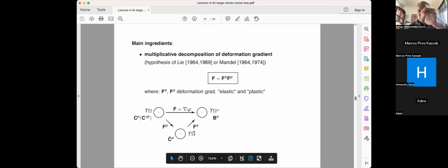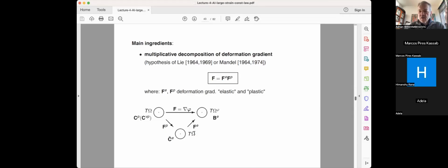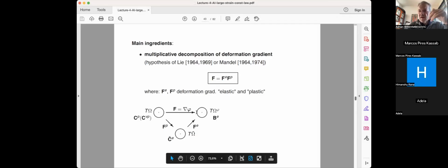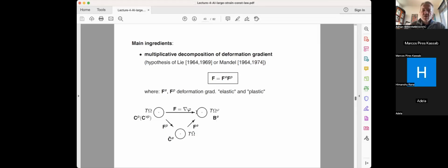It's just what is going on locally. But that fits with the description of how we deal with the plasticity computation in the finite element setting. Namely, recall when we are computing the equilibrium equation or go to dynamics, we have a dynamic motion equation. We are doing a global computation, but when we are computing the plastic deformation, let's say, or hardening variables and so on and so forth, these are just local computations.